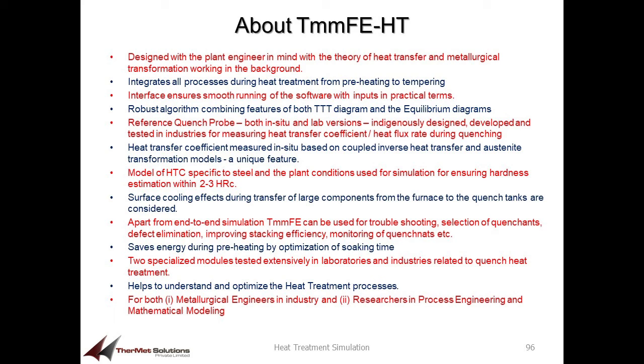So essentially the heat treatment simulation software is designed with the plant engineer in mind, with the theory of heat transfer and metallurgical transformation working totally in the background. So it integrates all processes during heat treatment from preheating to tempering. The interface ensures smooth running of the software with inputs in practical terms. A robust algorithm combining features of both TTT diagram and the equilibrium diagrams has been developed.